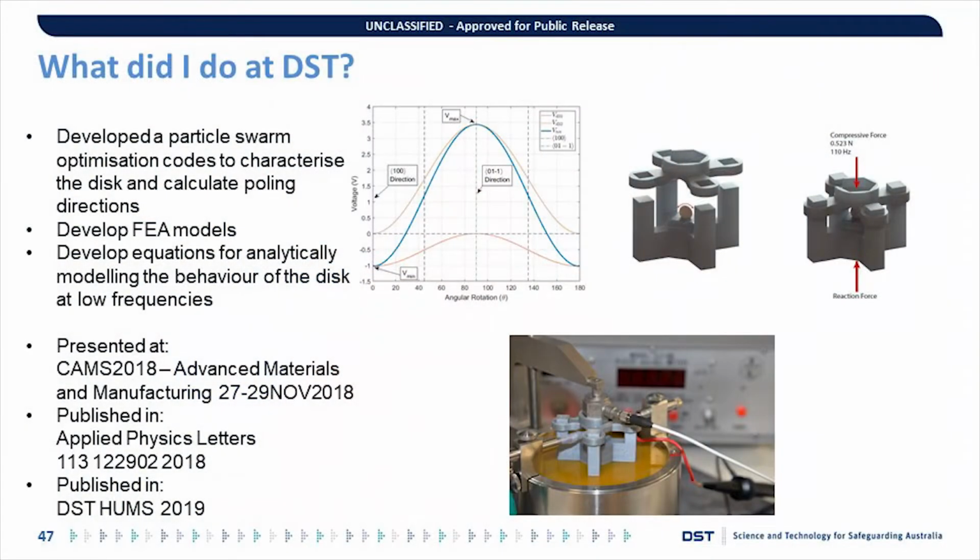So what I did during my time at DST was spend a lot of time characterising and profiling these relaxor ferroelectric single crystals and trying to find the material properties which define this behaviour. Also a big struggle was the fact that directionality was unknown, so these crystals were unmarked and we had to profile each individual crystal. One year ago we had to take the crystals to the synchrotron and perform X-ray crystallography, which is extremely time-consuming and expensive. We got that down to a 30-minute laboratory experiment.